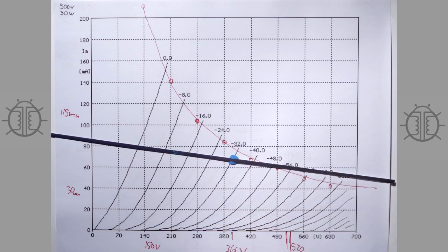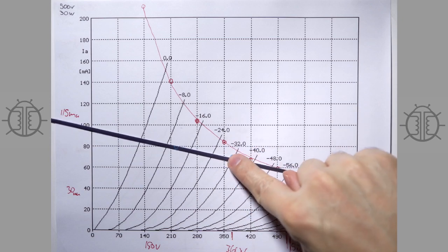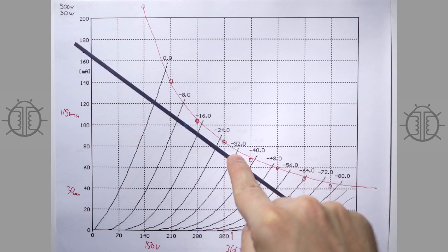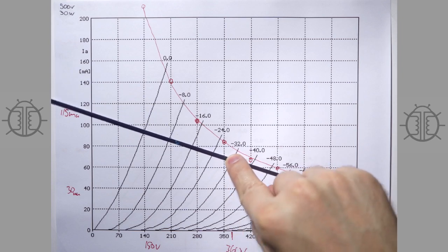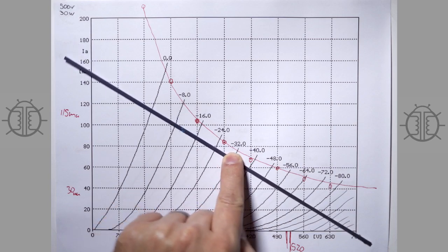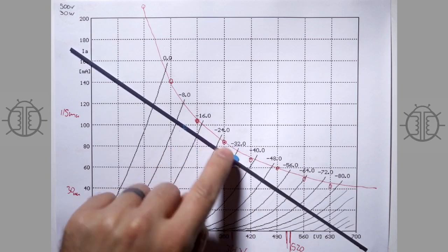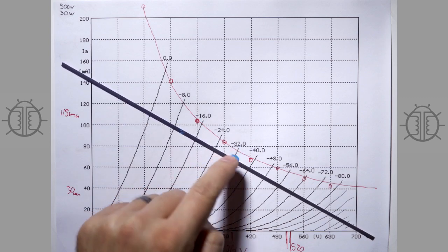which is why if you unload a tube amplifier and drive it, you can damage your components because the voltage will swing very high. So maybe you swing up like that, and then you get past resonance, and it goes back down like this, and then the high frequencies go up and your load line kind of flattens out again into those high frequencies. So this is not a fixed thing. This is highly dependent on the load that you're driving with the transformer secondary. So just keep that in mind.